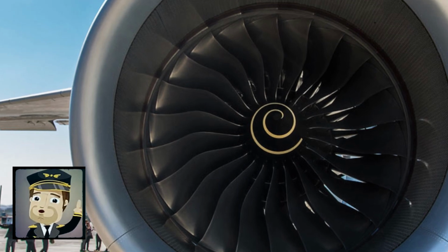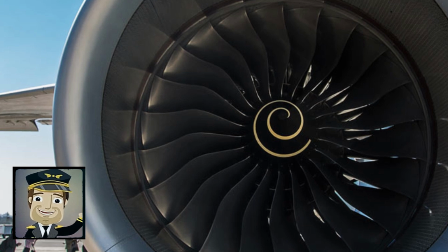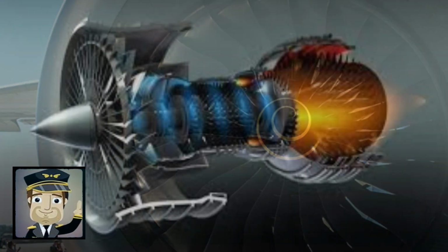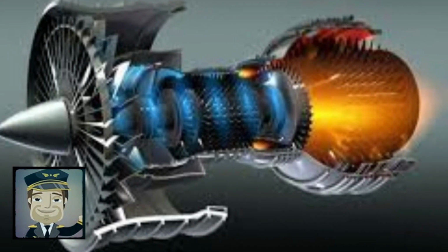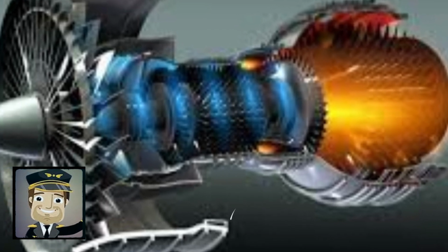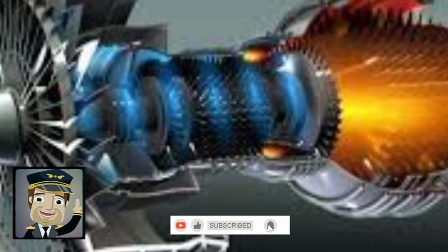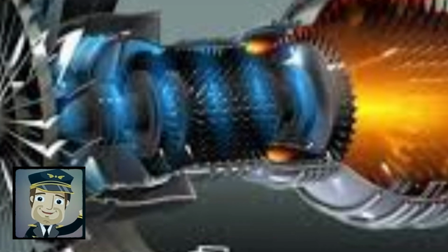In a turbojet engine, the high temperature and high pressure exhaust gas is accelerated when it undergoes expansion through a propelling nozzle and produces all the thrust. The compressor absorbs the mechanical power produced by the turbine. In a bypass design, extra turbines drive a duct fan that accelerates air rearward from the front of the engine. In a high bypass design, the duct fan and nozzle produce most of the thrust.